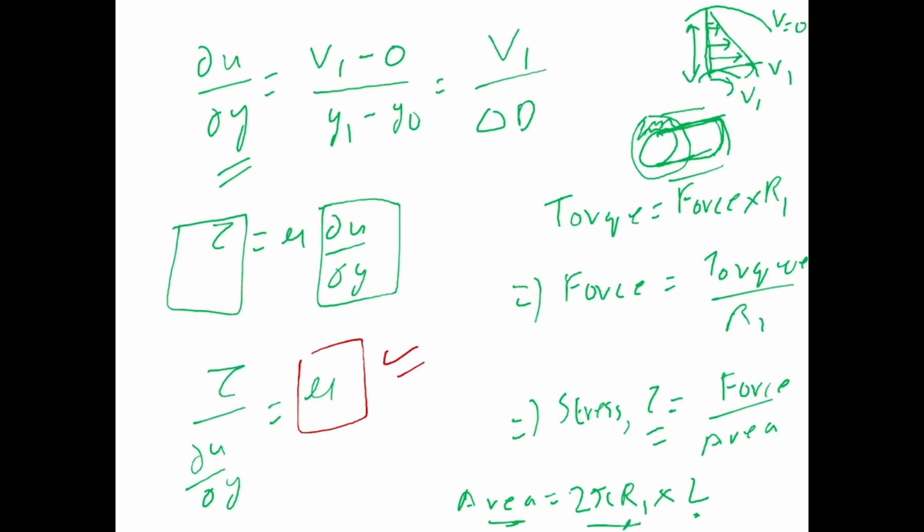So this is actually the way viscosity of a material, or a fluid medium, is determined. You have a device similarly where you have a rotation, you have two cylinders, and you can put liquid in between them. One of them is kept fixed with a sensor where you can measure the velocity, or rather the RPM, since it is easier to measure RPM. Then you measure the force or torque experienced by the cylinder inside, and you can use this basic linear assumption to calculate the viscosity as such, right?